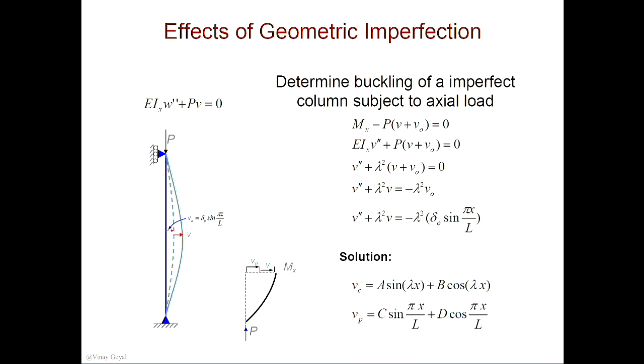And so when I go here and I develop the equations for this problem, you will find that if I divide everything by EI also, to kind of get rid of this EI, this is the governing equation for the problem at hand. And previously we had this as 0. But now we have an imperfection, so we have this part of the equation coming up.